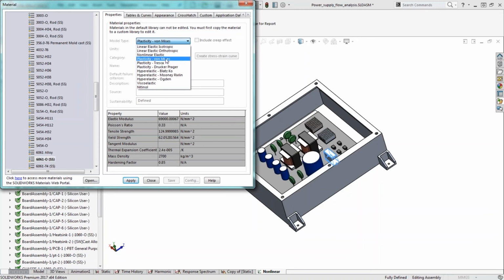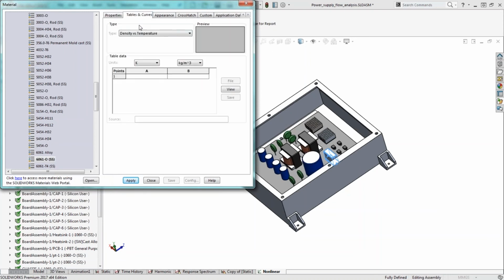So within a nonlinear study here, you see that it's the same setup in terms of defining some sort of material, but now we can input a stress strain curve, what's going to happen at post-yield, and this time we can account for this large deformation, so we're getting a true representation of how the stresses are going to be seen when we have this large load or this large acceleration that we're applying onto our model.